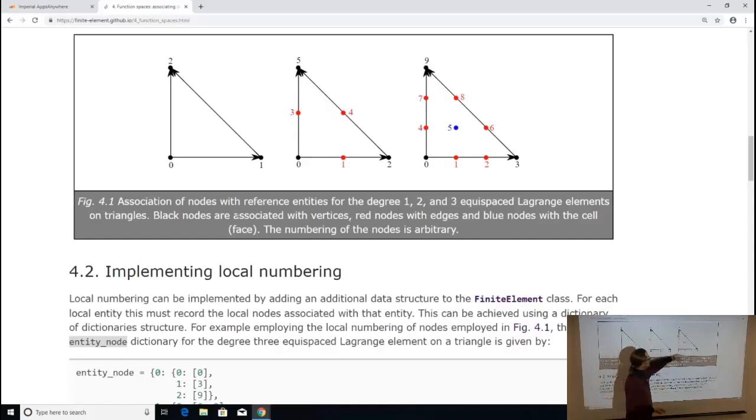And then in this case, I have the slightly more complicated case where I have suddenly got more than one entry on the edges. And so you have to make sure that on this edge, 1 comes before 2, because the edge goes that way, and so on. So if you number them the way around I number them, it turns out that they come out in ascending order. But that's an artifact of the way I numbered the element. It's not an intrinsic property. So you need to make damn sure that what happens for your one works.